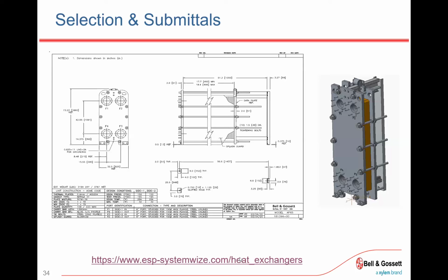Down here, NSF: if we were to have, let's say, a potable water system, then we'd want to select that. All that really does is give you a safety net to make sure that you select components that are rated for potable water. You don't have to select that to go through and make a selection. It just walks you through a little bit easier.